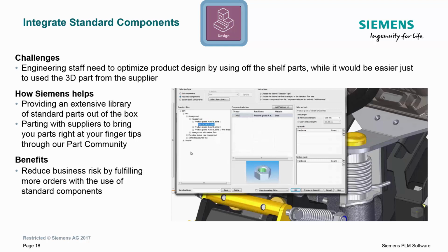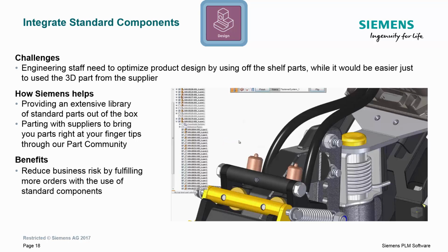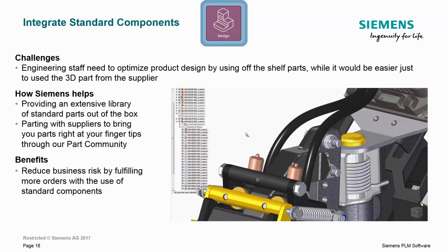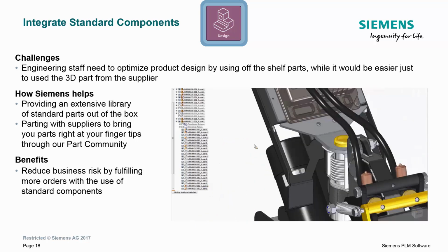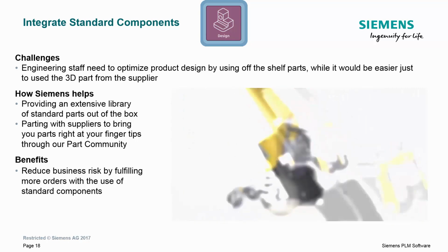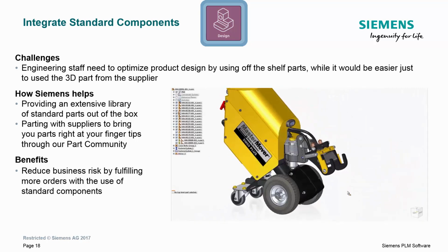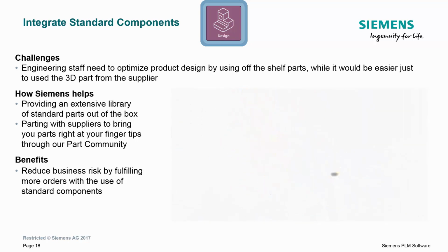These stacks of bolts, washers, and nuts are automatically determined based on a selection of entrance and exit holes in an assembly. A collection of fitting, standard fasteners will then be presented to the engineer to choose which set will work best. Once a fastener is selected, Solid Edge will automatically generate the parts and assemble them in place.